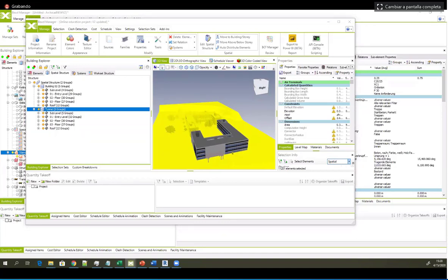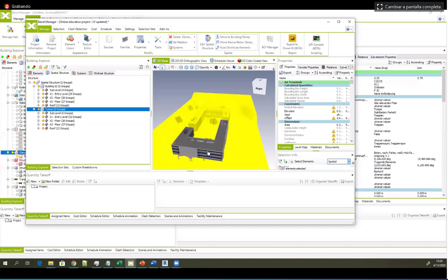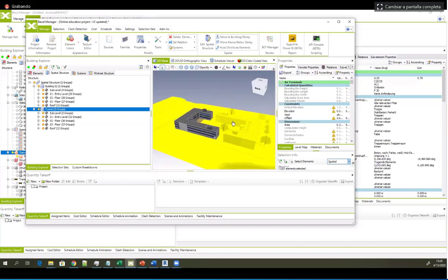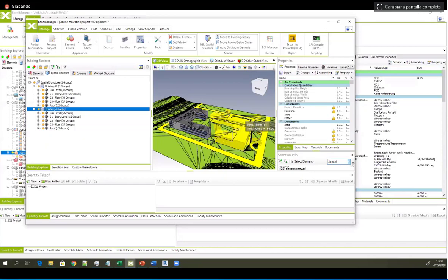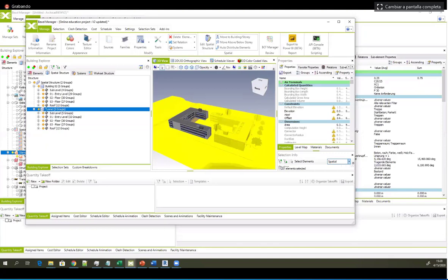The next question: why, when I publish a Revit model to BX3 and open it in Bexel Manager, does it not show Uniformat, MasterFormat, and custom sequence? Because you do not enter these properties within your Revit model. This sample model is created in Revit, and we added some additional properties or attributes, and then these properties are exported. So if you want to get Uniformat or MasterFormat or any other additional property, you have to specify that in your authoring tool.